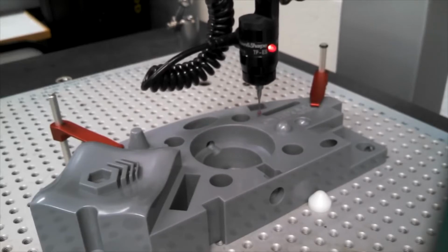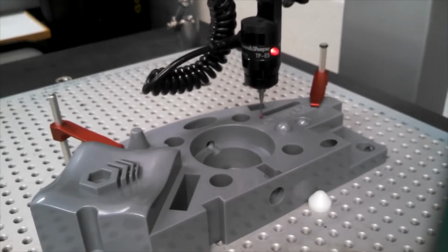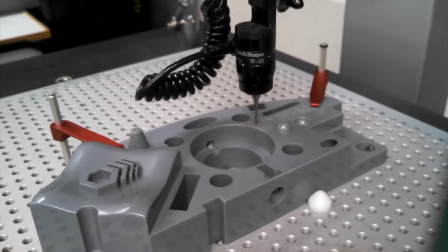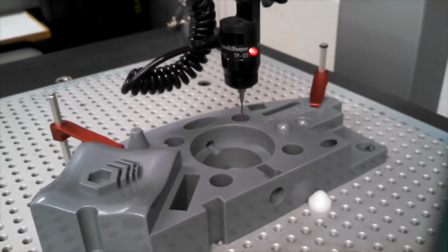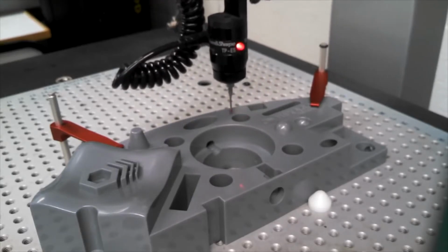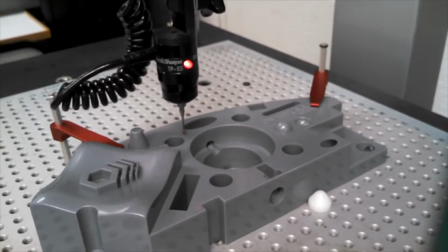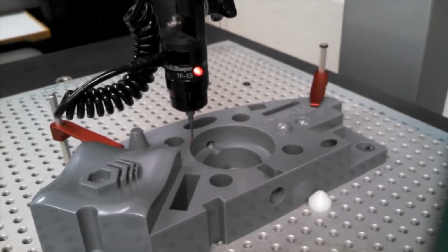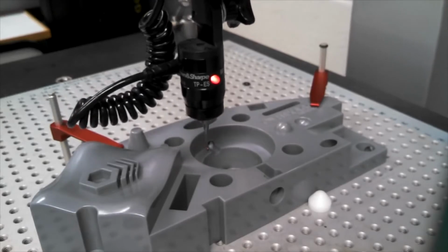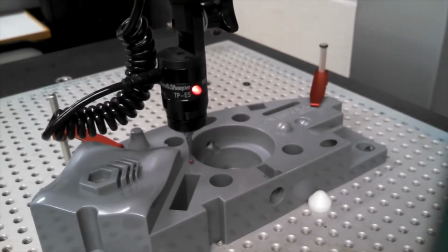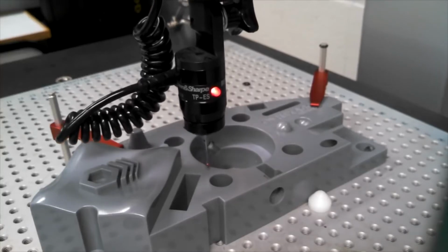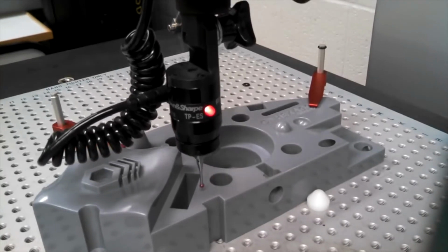In this example, a coordinate measuring machine sequentially probes the surface of the sample by sensing discrete points with a probe. This is a 3D bridge CMM, which allows probe movement along 3 axes, X, Y, and Z. Each axis has a sensor that monitors the position of the probe on that axis, typically with micrometer precision.